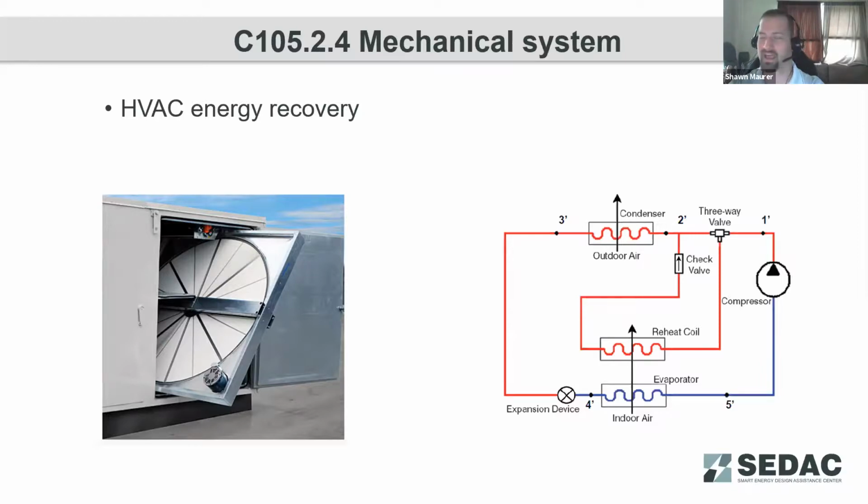There are other systems such as flat plate heat exchangers and runaround loops for cooling energy. They're typically used in lab systems where you cannot exchange air directly from an exhaust airstream with an energy wheel or an energy heat exchanger, because those systems would potentially allow some mixing of the exhaust and outdoor airstreams. So particularly clients that are looking for more outdoor air in a cost-effective way, there are other ways to add that air, particularly kitchen systems that may have a lot of grease. Runaround loops, or other heat exchange systems that exchange sensible heat, may be more economical now.